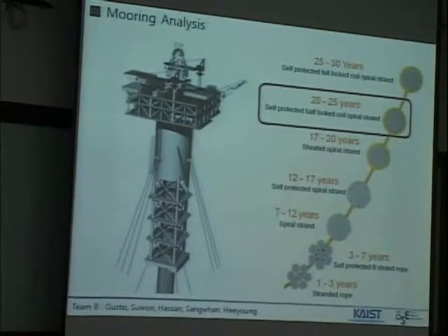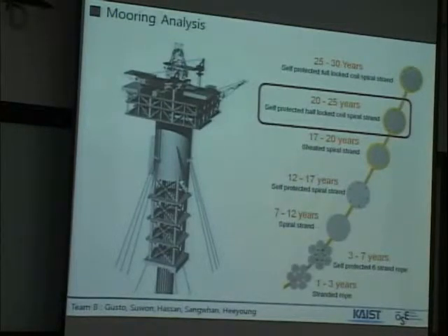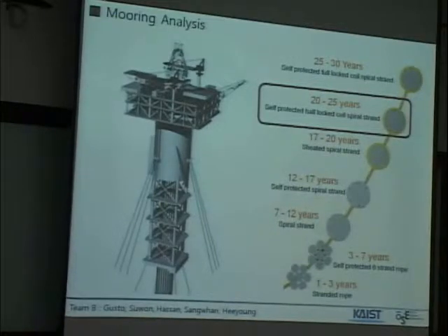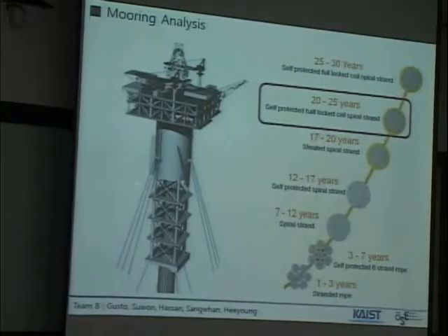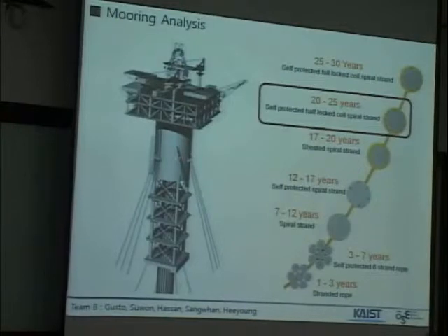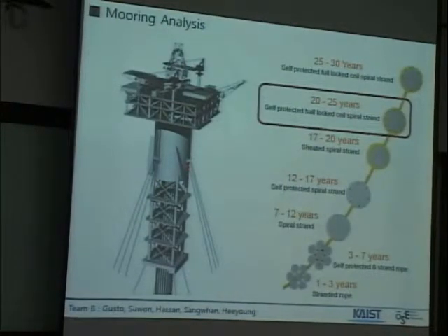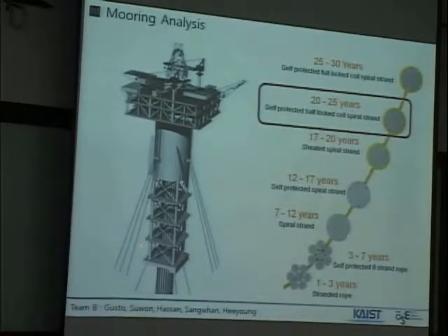And by using these exciting forces and moment, we can calculate how many wires will be needed and which diameter is suitable. In order to fix this floating structure in wave condition, we need some tight mooring wire to catch this floater with the sea bottom.